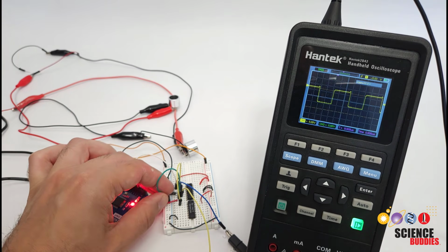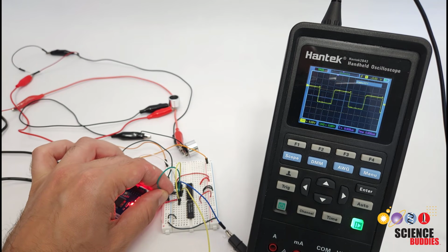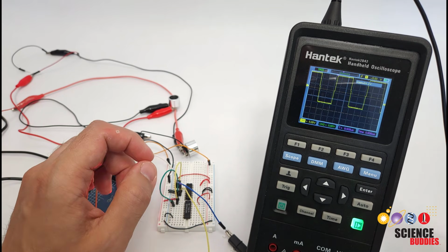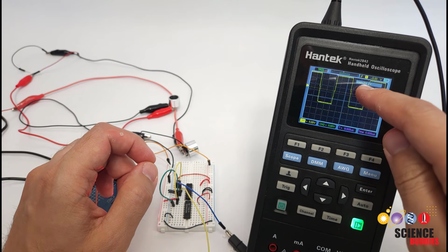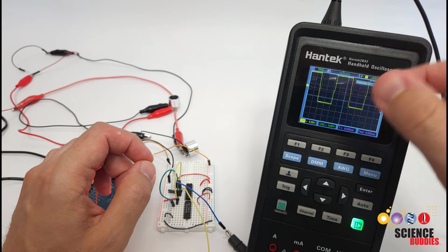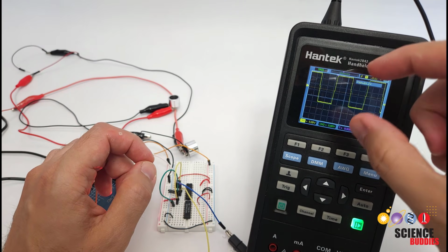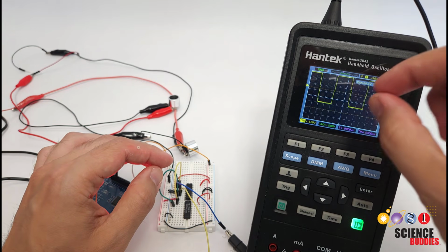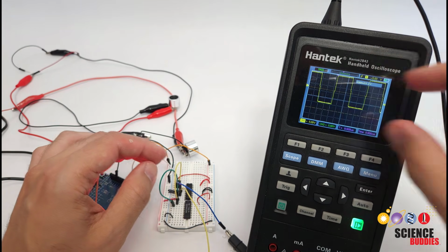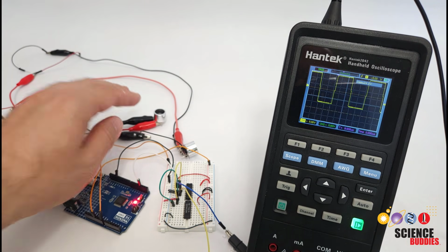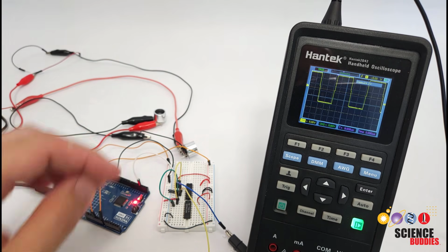But if I take the jumper wire that is currently grounding one pin of my H-bridge and connect it to the output of the inverter, as I just demonstrated in Tinkercad, the voltage amplitude or peak-to-peak voltage jumps up to 24 volts because now we are flipping between positive and negative 12 volts applied to the transmitters. So again, I have doubled the amplitude of the voltage applied to my transmitter. That's going to give me more powerful sound and in theory result in a better or more powerful levitation effect.